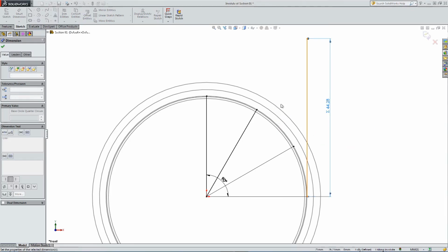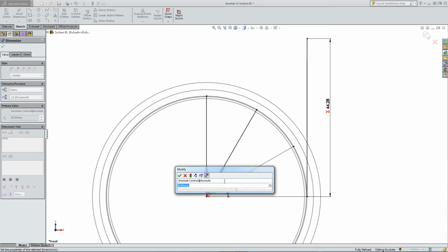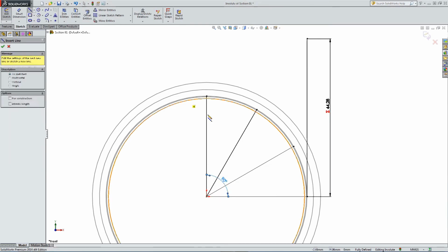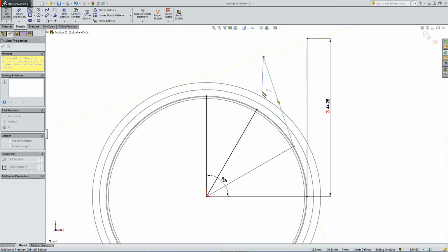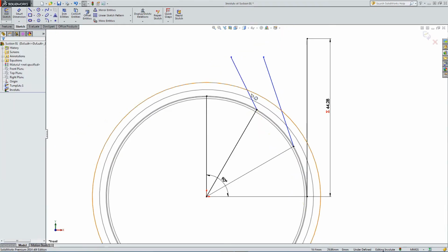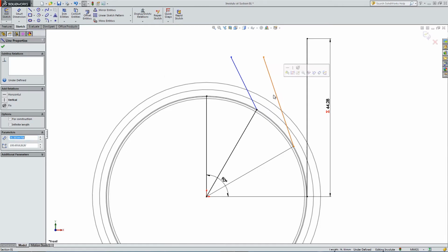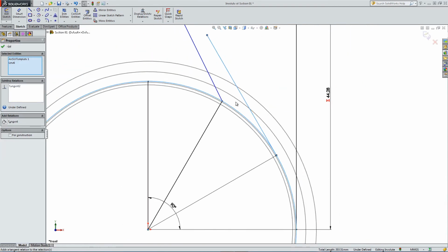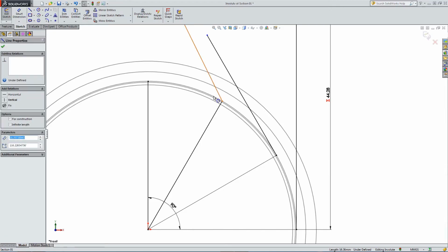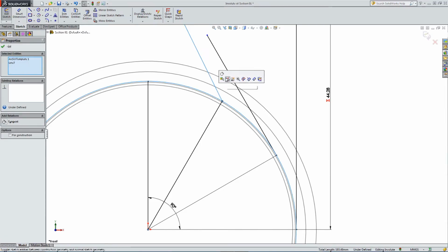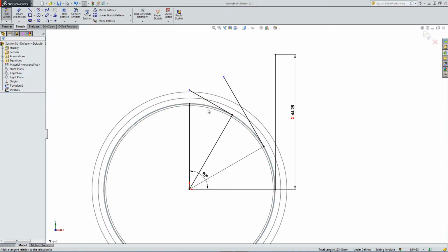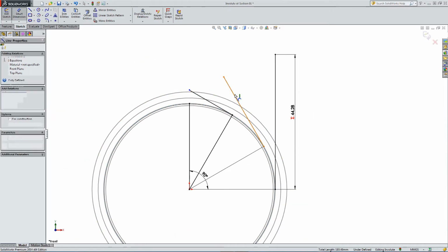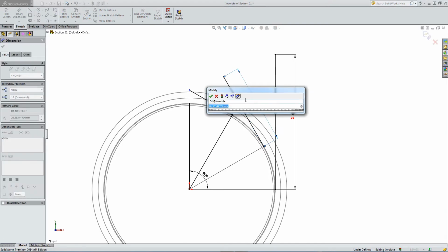So we've got our first reference line. Let's draw a second one, a third one. Okay. So now we only need 2/3 of the circumference at the second reference and 1/3 of the quarter here to form the involute. So we can derive this through an equation.